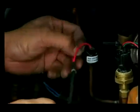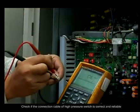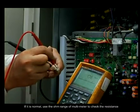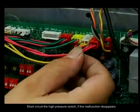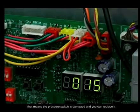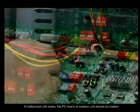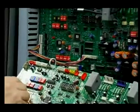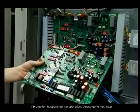Step 1. Check if the connection cable of the high pressure switch is correct and reliable. If it is normal, use the ohm range of a multimeter to check the resistance. If it is open or infinite, that means the switch is broken. Short circuit the high pressure switch. If the malfunction disappears, that means the pressure switch is damaged and you can replace it. If the malfunction still exists, the PC board of the outdoor unit should be broken. You have to replace it with a new one. If protection happens during operation, please go to the next step.